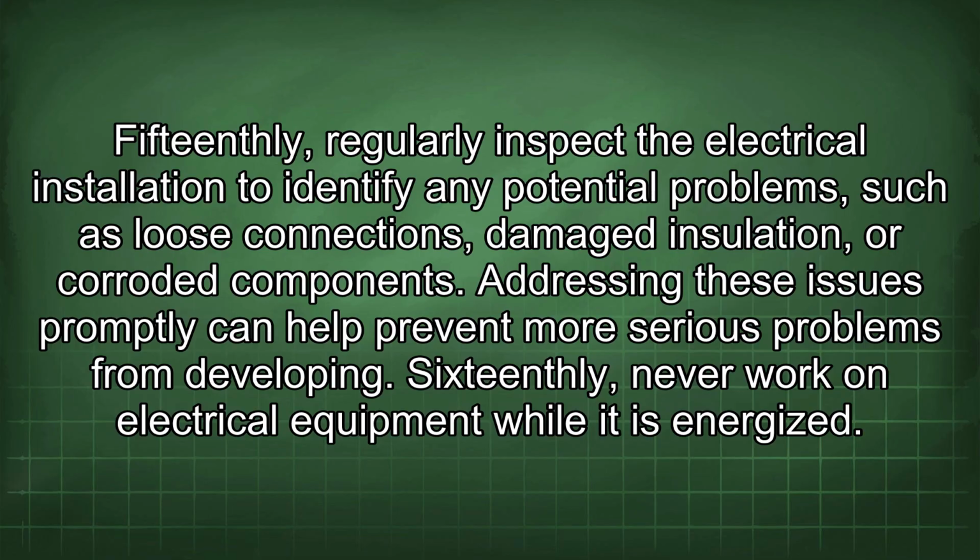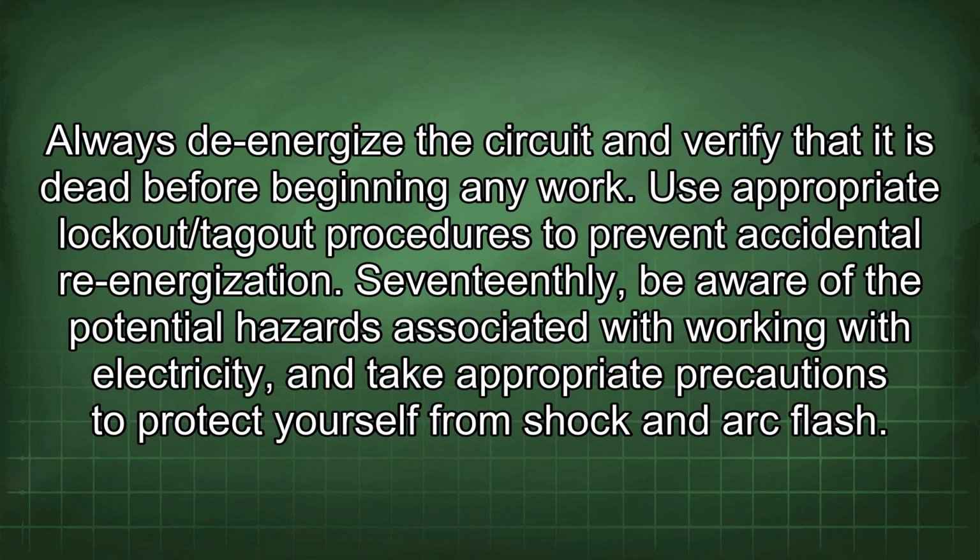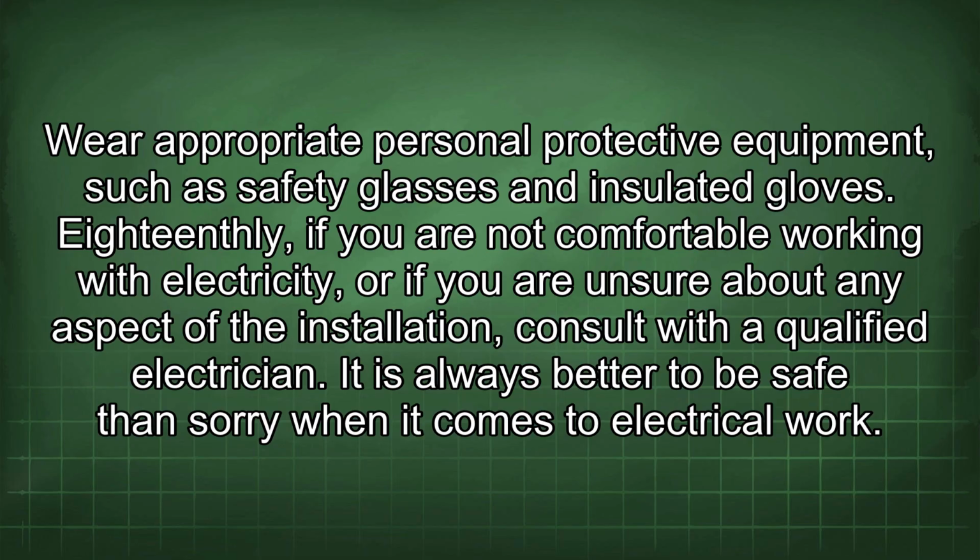16thly, never work on electrical equipment while it is energized. Always de-energize the circuit and verify that it is dead before beginning any work. Use appropriate lockout/tagout procedures to prevent accidental re-energization. 17thly, be aware of the potential hazards associated with working with electricity, and take appropriate precautions to protect yourself from shock and arc flash. Wear appropriate personal protective equipment such as safety glasses and insulated gloves.